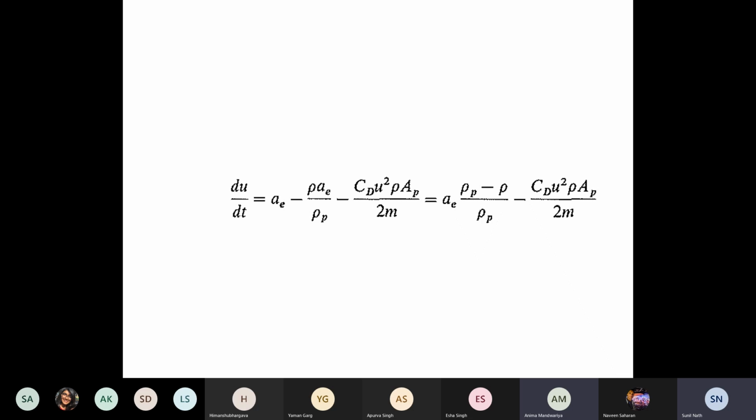then knock off the acceleration term du/dt. I said that you will get a general expression which is shape independent. Nowhere have we assumed anything about shape, nowhere anything about hydrodynamics. So a hydrodynamic regime independent, shape independent expression you are going to get for a maximal velocity, or terminal condition velocity, u subscript t or u subscript m. So I said, please solve for that and tell me what that expression looks like. Yes, sir. I will do.